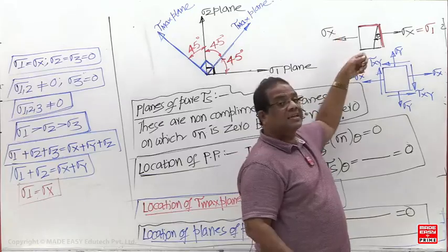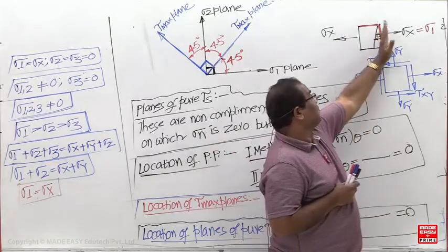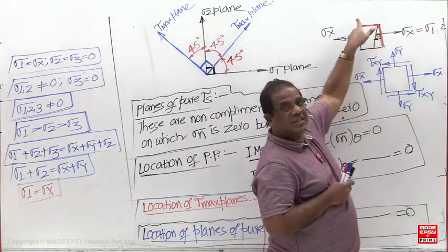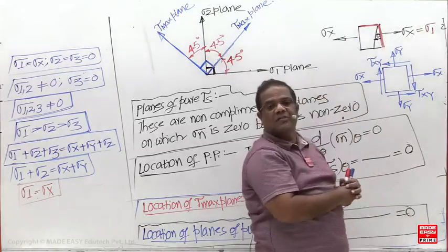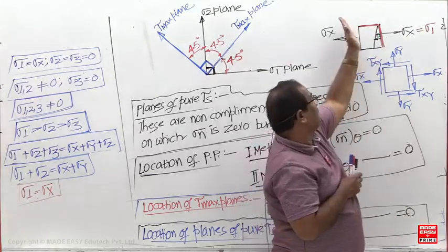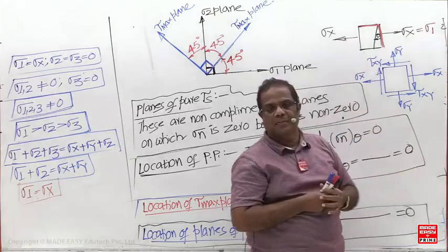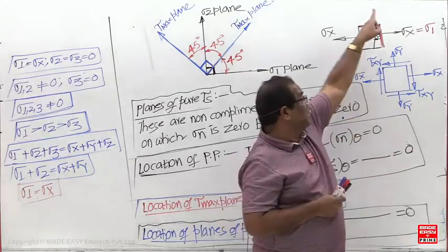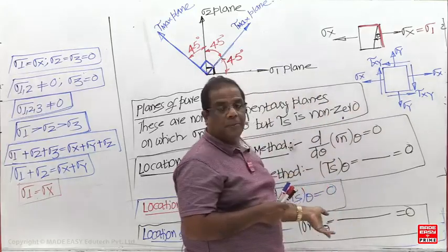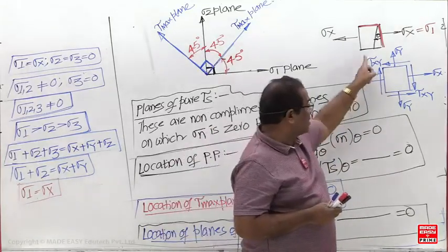But in the uniaxial case, you directly know. Why? On the x and y faces shear stress is 0. Directly these planes are the principal planes. And directly the diagonals are which plane? Once you know the principal plane, directly the diagonals are the tau max plane. Principal plane and tau max plane are at an angle of 45 degrees. So in that case, are the equations compulsory or optional? Optional. But in this case, compulsory.